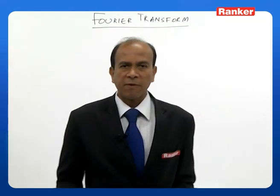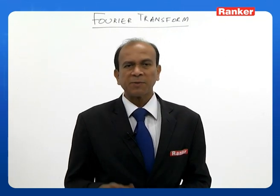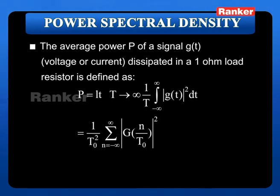Now let us look at power spectral density on similar lines as we have seen energy spectral density. So what is a power spectral density? The average power of a signal g of t, whether it is a voltage or a current, dissipated in a 1 ohm load resistor is defined as P is equal to limit T tends to infinity 1 by T integral minus T by 2 to plus T by 2 mod g of t whole square dt. This is in fact equal to 1 by T naught square summation n equal to minus infinity to plus infinity mod G of n by T naught whole square. So this is known as Parseval's power theorem.